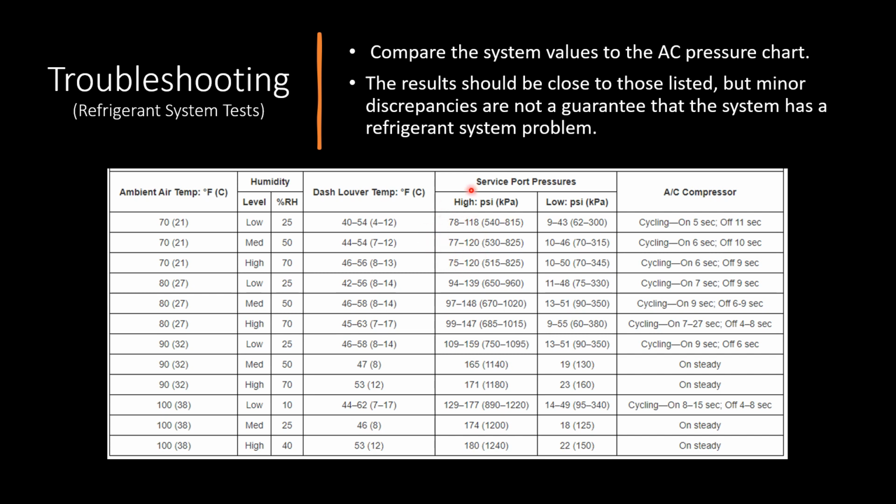You're going to want to see these pressures here, right? So that's what you're going to want to see. Now, remember that these pressures are specific to the vehicle that I'm working on. They're going to change on every vehicle depending on the type of compressor they have. So if the compressor is different, then these pressures are going to be different.